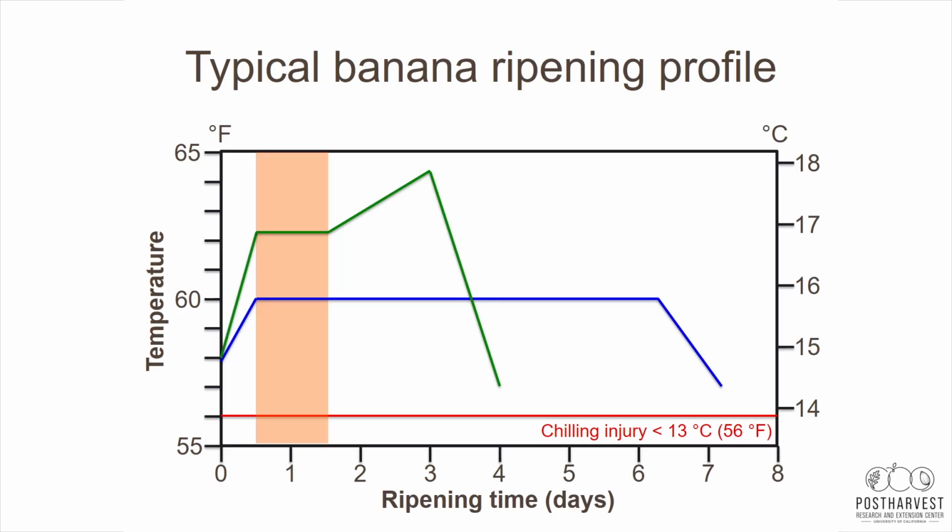As I've said in the beginning, if the CO2 levels in the case of bananas get above 1%, that might affect the quality of the produce. Therefore, in any case where we're ripening, we need to vent the air as CO2 increases significantly. And I'll give you some rules of thumb basically on how to keep this, but generally speaking, we need to keep the levels of CO2 below 0.5 to 1% or lower than that.